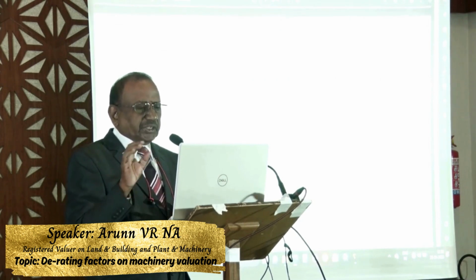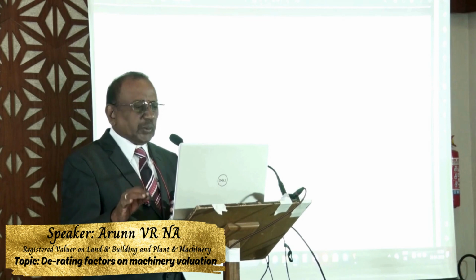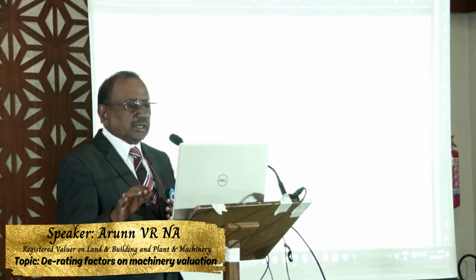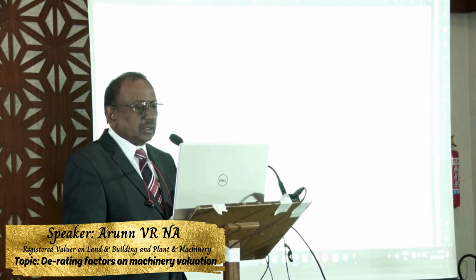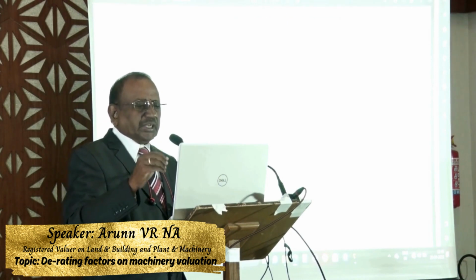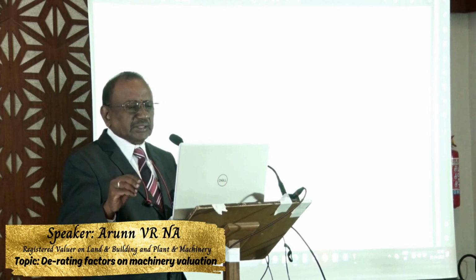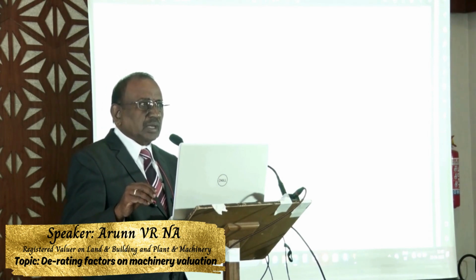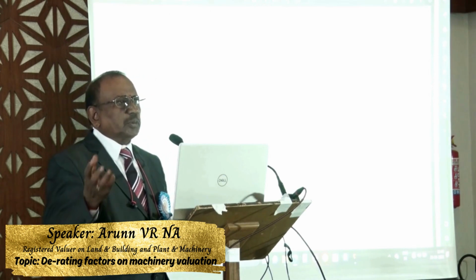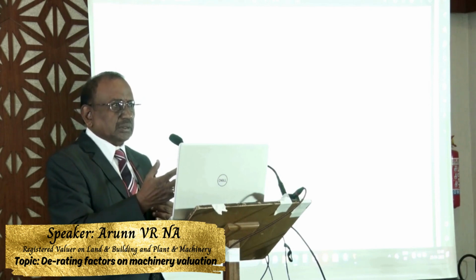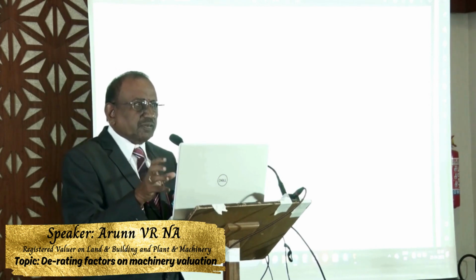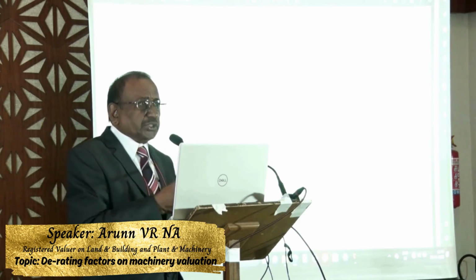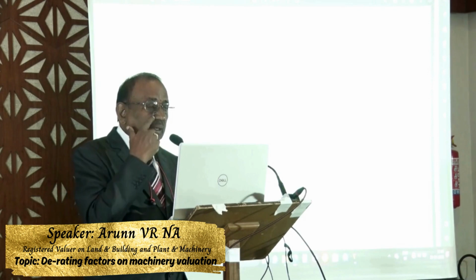Fair condition: if a machine delivers goods lesser than the rated capacity and it requires general repairs and or minor replacements to raise the level of utilization to near the rated output, it is classified under a fair condition. Poor condition is where the machine delivers output very much lower than the rated output, and it requires extensive repairs or replacements. What is the use of spending so much money to see that your old machine is rectified and made into a good machine? Component-wise, if the cost of inputs to make it more useful is more than the cost of the new machine itself, then it is in poor condition, which is not required.